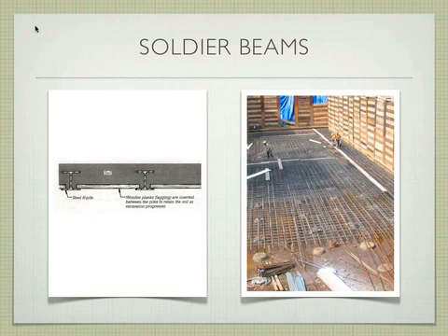What do you call that wall on the right hand side? Here, it says wooden planks or lagging. Are those wooden planks set below the grade of the foundation, like a footing? These won't typically remain after the foundation is set, and we'll get to this. These are a temporary system that's going to shore up the wall and be removed after you pour concrete. So theoretically, you don't need to put forms below where the finished grade is going to be anyways. Right. So this is just a temporary way of retaining all the earth that's on the other side of that. There are permanent ways that we'll talk about in a second.